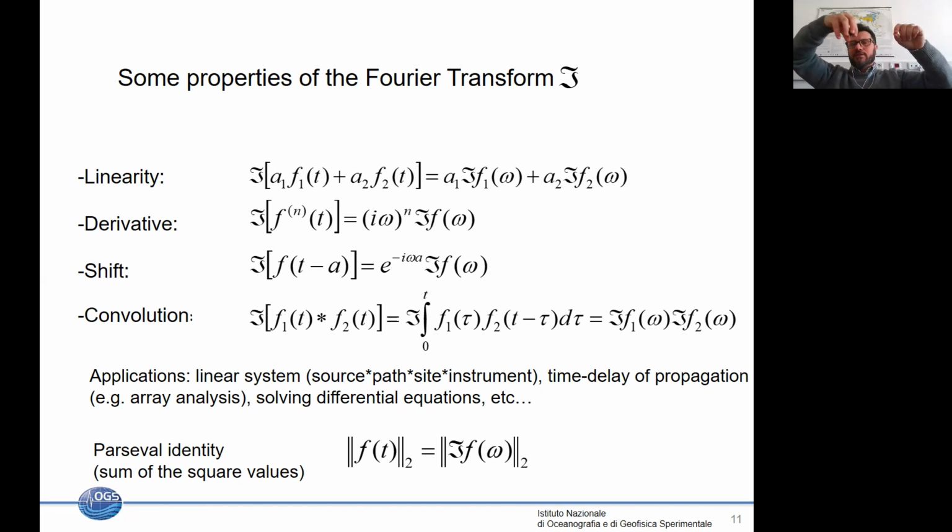And then this pulse will propagate to the next sensor, to which it will arrive a little bit later. So if you plot these two recordings, starting at the time when you use the sledgehammer, you will see a time series with a pulse and another time series with a pulse at a time which is a little bit late. It's like you're adding a certain amount of time delay, a quantity A, to this pulse.